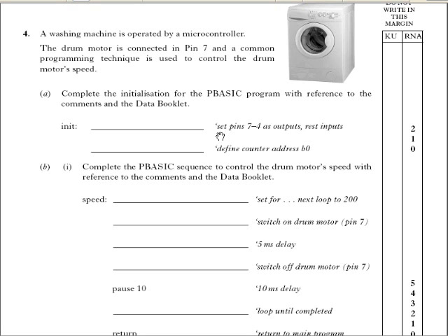The command to do that is let dir. Let dir sets the data direction register. To set an output, you put in a 1. So we let dir, then the percent symbol to tell the computer the next value coming is in binary. So it's let dir equals percent 1 1 1 1 and then 4 zeros.